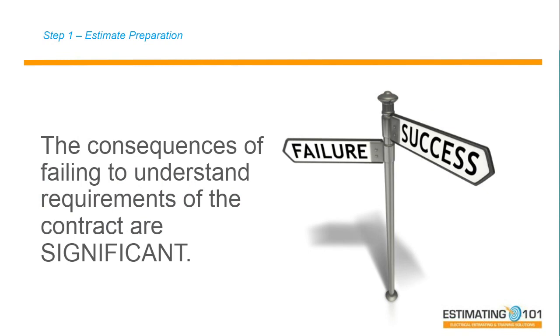I didn't say in the beginning, but I will say I have made almost every mistake you can make as an estimator. I've made lots of them. But there is one mistake I have not made. I have never bid or estimated a project that was an explosion-proof hazardous location and taken that project off an EMT conduit. But I do know an estimator that did. And so it is vital that the estimator understands how to interpret the specs.